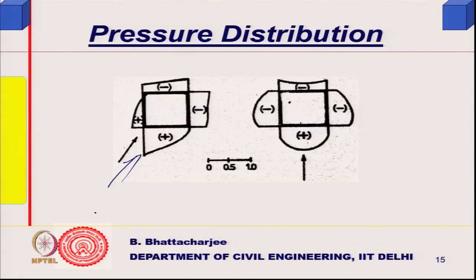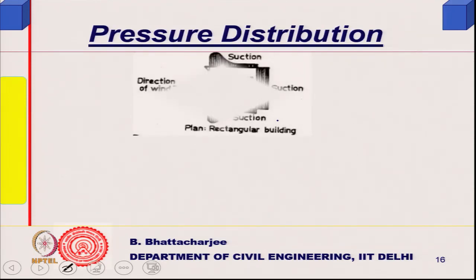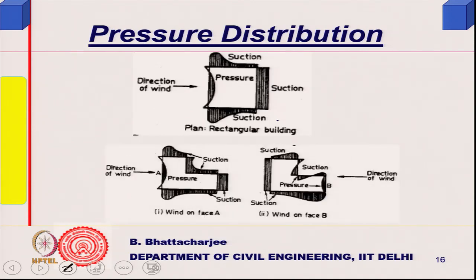So you can see that normal wind and 45-degree wind we are considering. With 45-degree wind, you will have excess pressure here, negative pressure here, and negative pressure here. With normal wind, positive pressure here, negative pressure here, some negative suction, and they will vary in this manner. That is another diagram showing the direction of the wind and suction, etc. One should be able to visualize this.